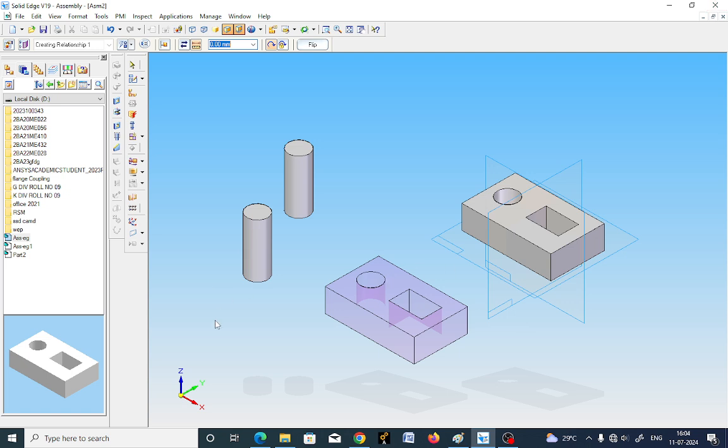Okay, now let us see using the options here, assembly options. This is what assembly relationship, as I said, a flash fit. Okay, so planar align, that's what align. Coaxial, that is what axial alignment. You got to insert here, you got a parallel, you got to connect, you got a angle, you got a tangent, you got a cam, you got a gear, you got to match coordinate systems of the components. Okay. As I said, major options are planar align, axial align, and mate.